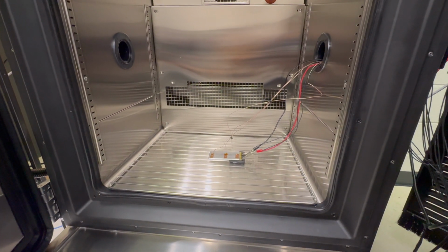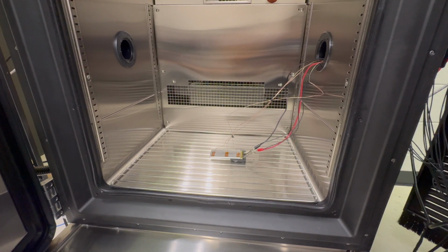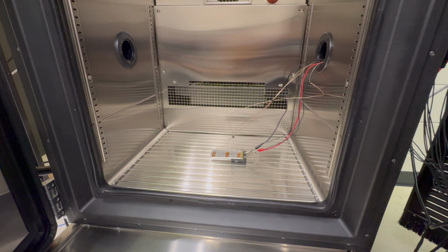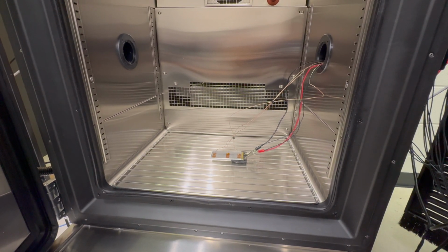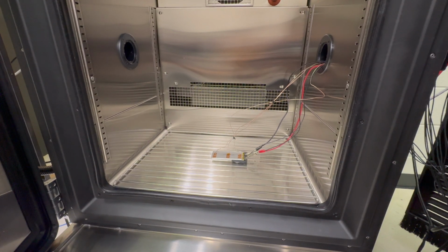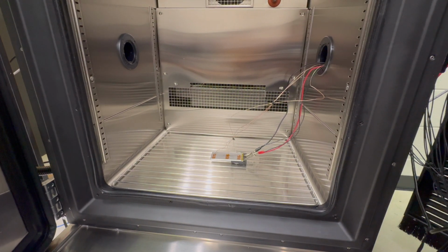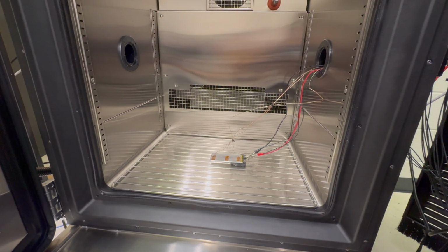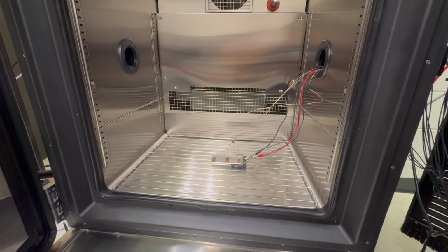Upon initialization, we check the voltage of the battery. If it's less than our threshold of the max charging battery voltage of 4.2 volts, then we initialize the power supply into a constant current charging of 1C, which in this case is 3 amps, and we charge that battery until it reaches the max charging cutoff voltage, which is 4.2 volts.